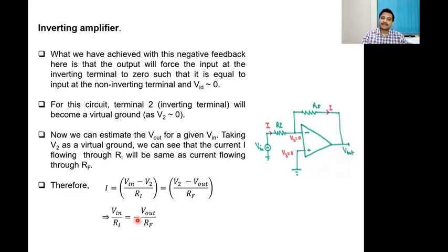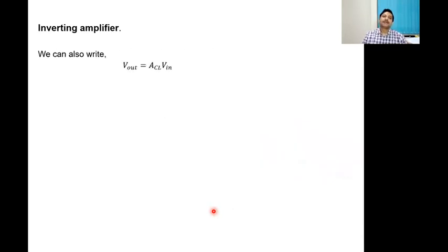or we can characterize this in terms of the gain of the operational amplifier. Right? So V out is simply minus Rf over Ri V in, and from this expression I can get the voltage gain for this feedback configuration as V out over V in, the actual input voltage in comparison to the measured output voltage, and call it gain. So V out can now be written as the voltage gain of the amplifier times the input signal, right?